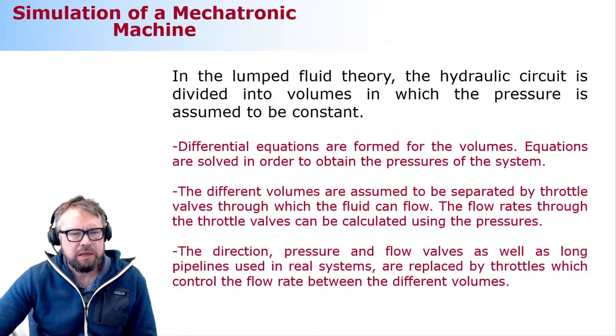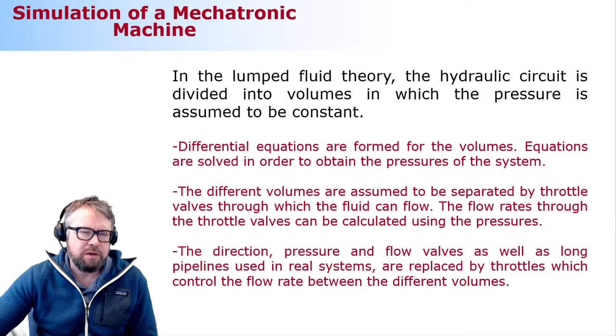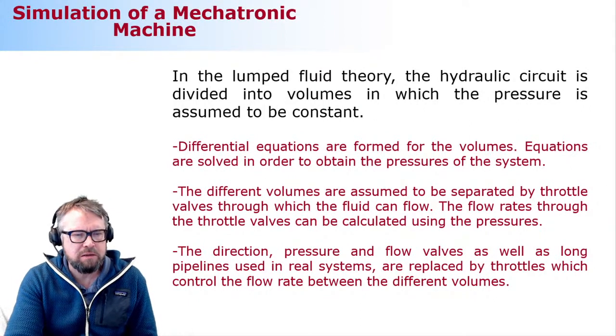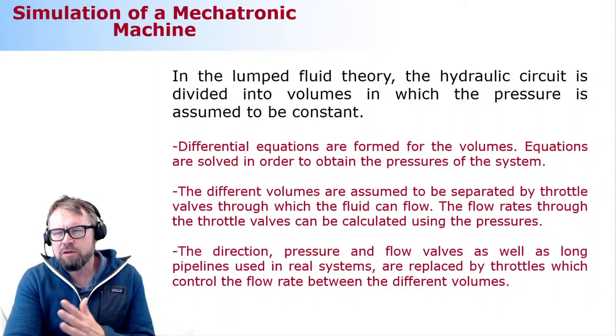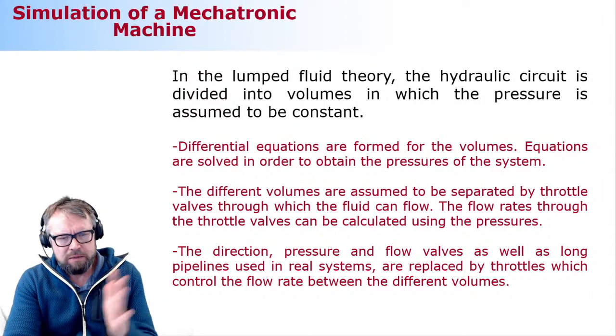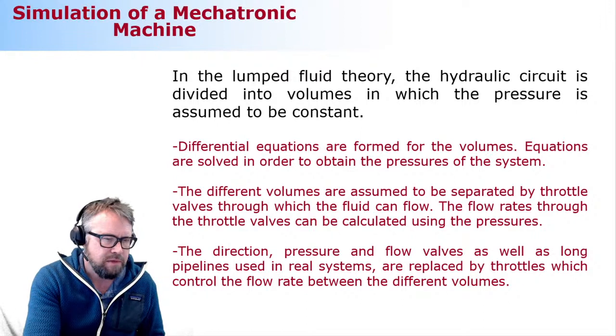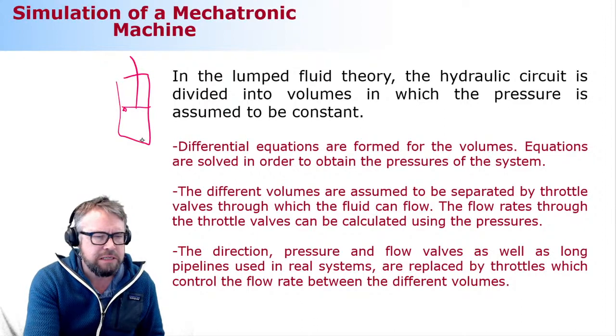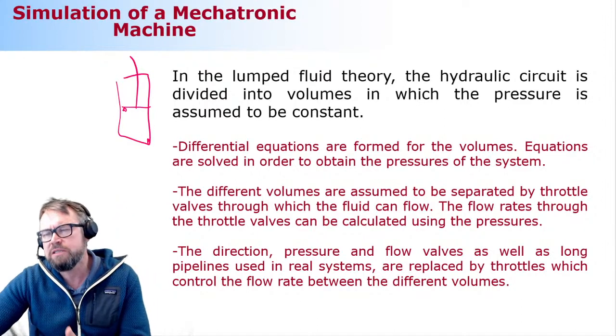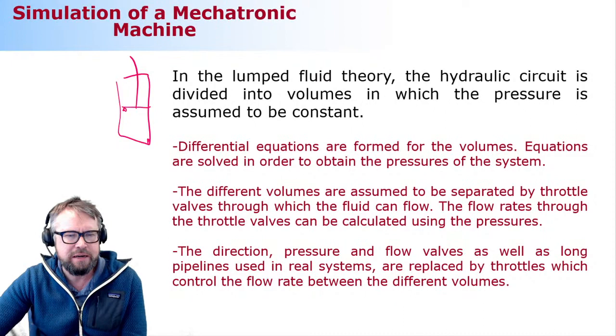So the pressure within the volume is assumed to be constant all over. It's not constant as a function of time, but if I have, say, a hydraulic cylinder like this, I'm assuming the pressure in this corner is the same as the pressure in that corner. That's what I would like to say here.